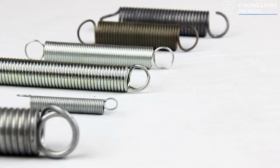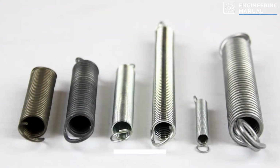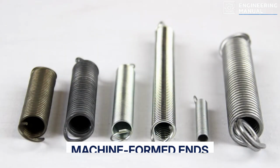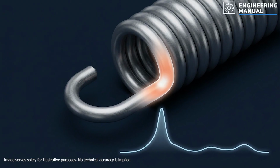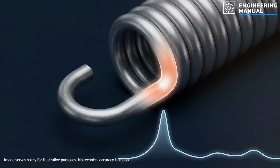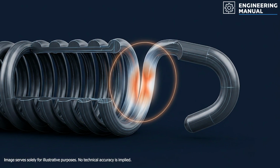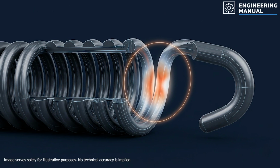The most critical design limitation is the end geometry. Hooks, loops, or machine-formed ends introduce abrupt stress concentrations that often govern failure long before the coil body reaches fatigue limits. In many cases, the wire does not fail in the helical section at all. It fails at the transition into the hook.